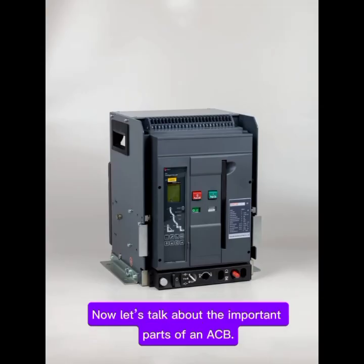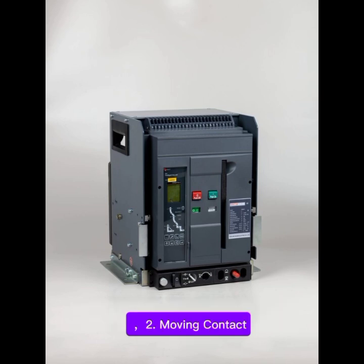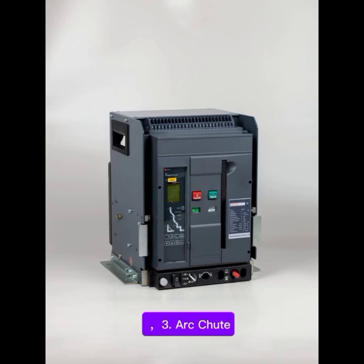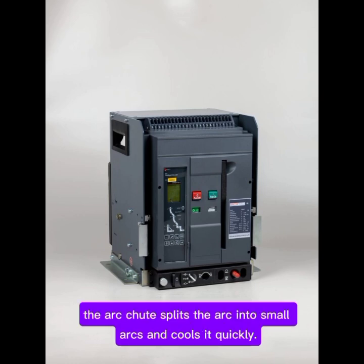Construction, main parts of ACB. Now let's talk about the important parts of an ACB. 1. Fixed contact. This contact remains fixed inside the breaker. 2. Moving contact. This contact moves when breaker opens or closes. 3. Arc chute. This is one of the most important parts when arc is produced. The arc chute splits the arc into small arcs and cools it quickly.